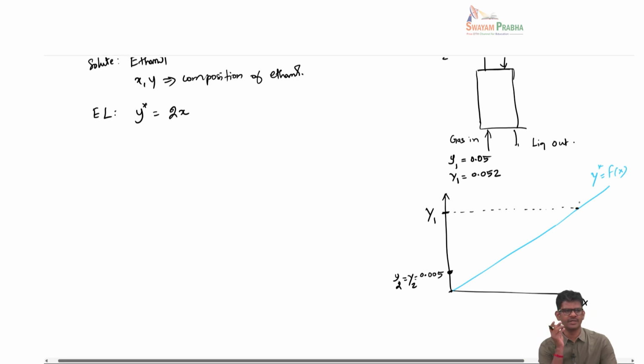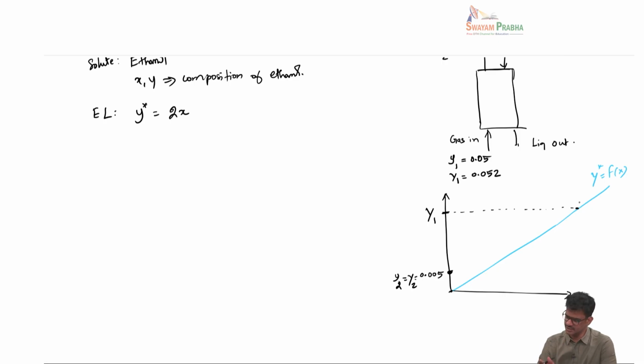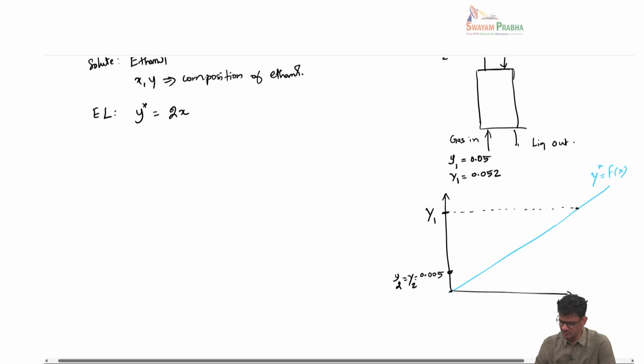So generally, when we look at the minimum liquid flow rate, we assume that the equilibrium line will be curved, and then the operating line should be the one that has the slope barely touching the equilibrium line, if it's a curved line. But here I said that this equilibrium line is almost linear, and your operating line is also linear. We know that in the units of mass mole ratios. So what we want to find out is, you have to draw a line from here to here.